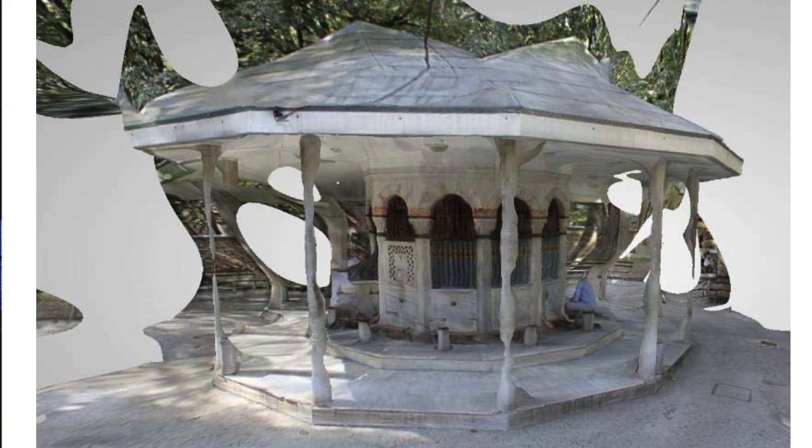So one of the challenges we ran into here is you get very, very distorted geometries, because the software can't distinguish one photograph from another. One of the things we also forgot to mention a little bit earlier is that the goal of having each point found in at least 3 photographs is really critical as you're doing this. But when the computer can't distinguish which points come from which surface, you get very, very distorted geometries.